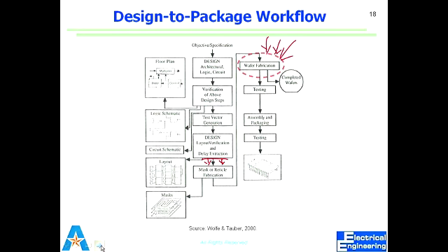So now they have made something which is physically transferred to a transparent plate, a quartz plate. And that is what we then take to transfer the design onto the wafer. So wafer fabrication, the red circle, is essentially what we'll be spending the next 16 weeks on. And then once you get it, we test it, we characterize it, and it goes into packaging.